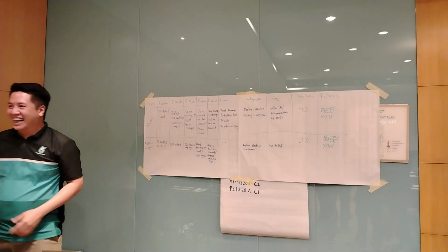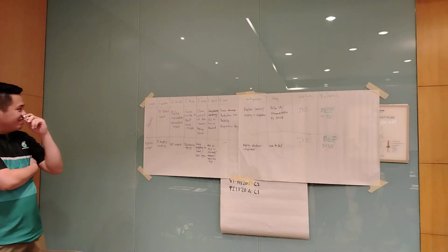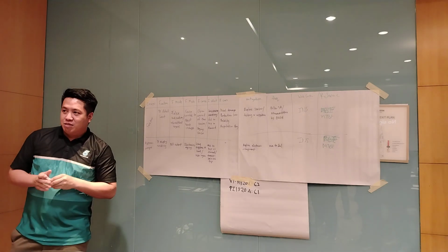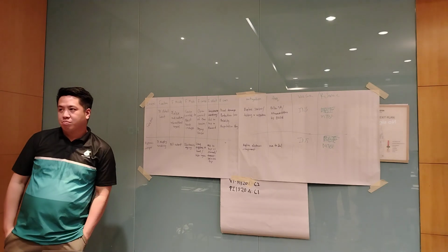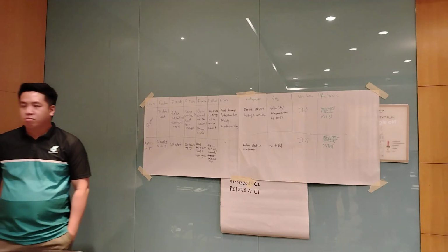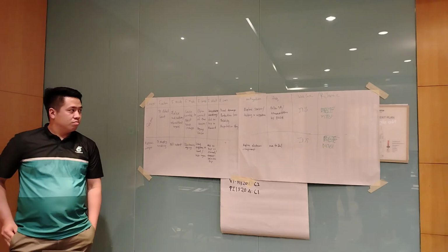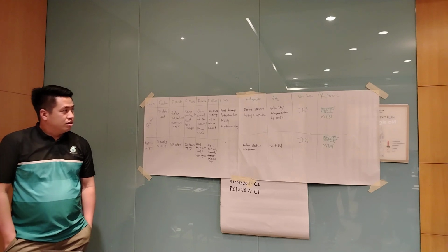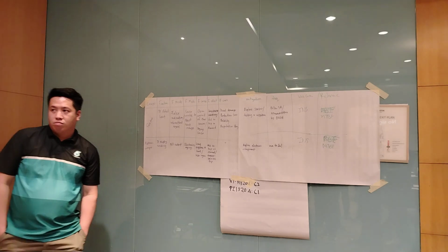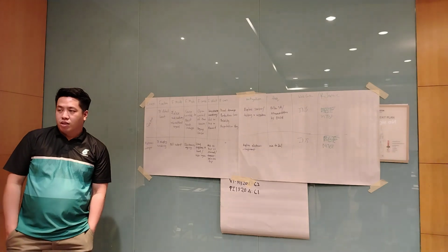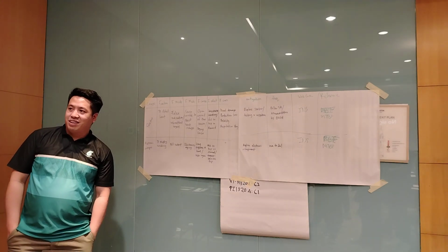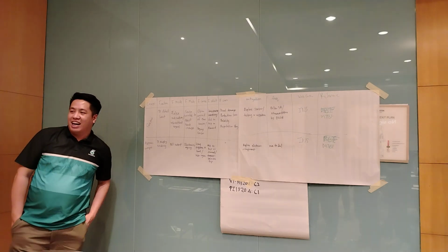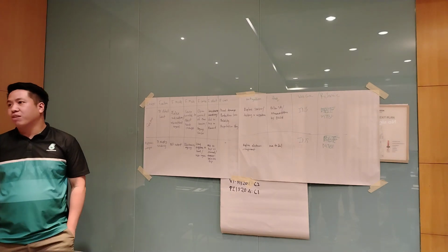Next, I will. For failure cause you said aging sensor. Right, so this aging sensor will cause it to be unable to detect the change and so on. So our mitigation is to replace the sensor and perform testing and inspection, with the interval following the TA and recommended method. But how long can your sensor last? Based on my record, 20 years still working fine. Usually maybe 5 years is still working fine.